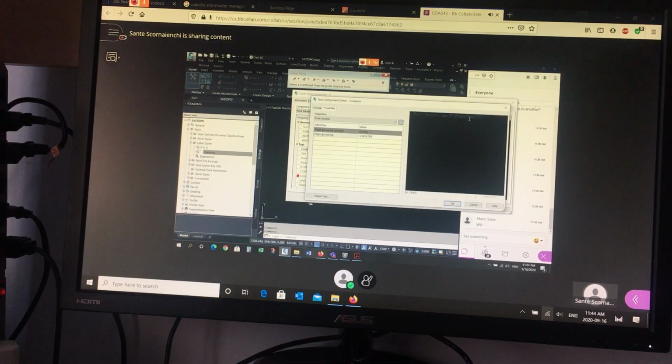I'm going to use that word. Please don't be intimidated by it. But this is the instruction. It tells you the units are in meters. P3 is 3 decimal places, and so on. These are all the settings. If you click on that text string, it shows you what all the different settings are. If I want to change the decimal place accuracy from 3 decimal places to just 2 decimal places, I have to change it here. This is your wish list. This does not take effect unless you hit this arrow right here.